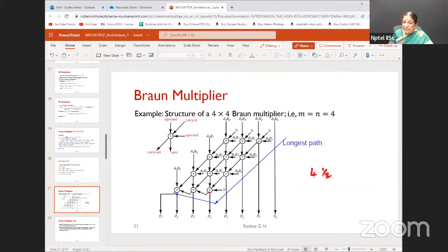I have considered this also as a full adder. That's why the result was 3 half adders and I had taken it as 9 full adders. Conceptually, if I consider everything as a full adder, I don't need to design the half adder, because that would increase my circuitry, with OR gates and exclusive OR gates to get the result added with the carry.